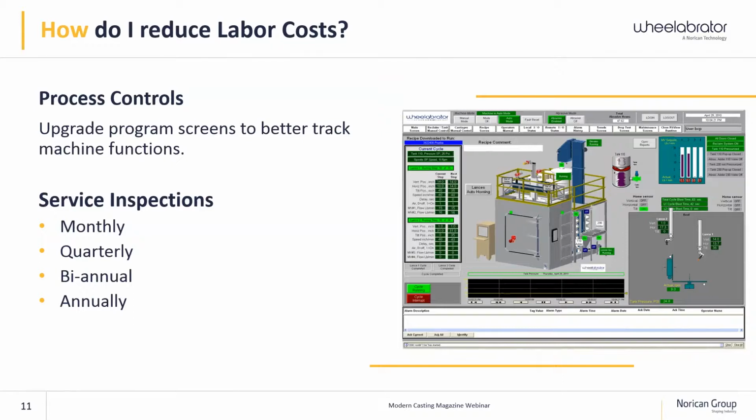You can put sensors all over it that can tell you vibration, sensors on wheels. Obviously, if your elevators, your screws are tripping out, if they're getting overloaded, you want that machine to shut down. If you've got a really highly processed part that you're trying to clean, you can actually set your system up to where if you drop below a certain level of amps being thrown, it will shut down your process.